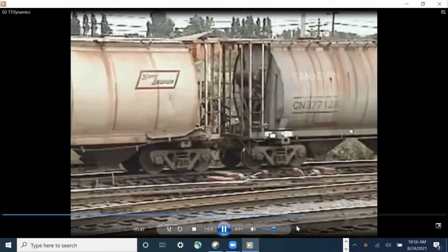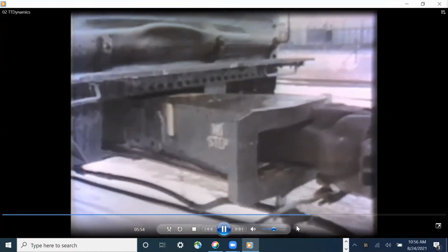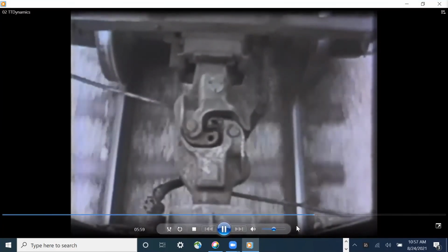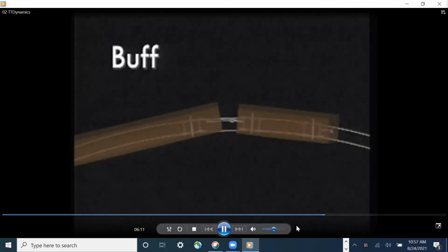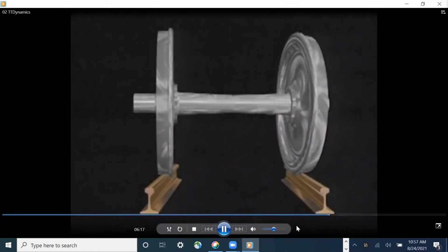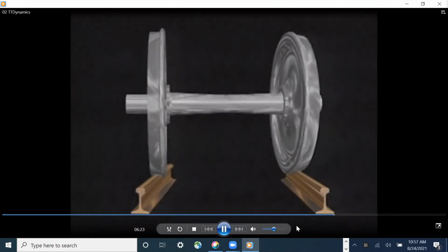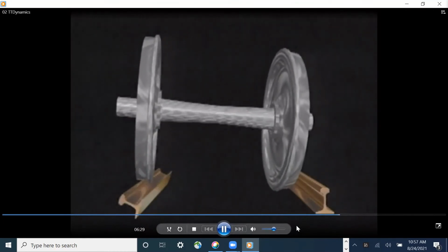Another similar lateral force is produced by buff and draft, which are measures of the in-train forces that pull and push on the individual vehicles in a consist as the slack in a train runs in or out due to changes in speed or grade. Buff forces in a curve push the truck assemblies of coupled cars outward. The additional lateral force increases the probability of out-of-line and wide gauge, or possibly low rail wheel drop, and the resulting high rail rollover.